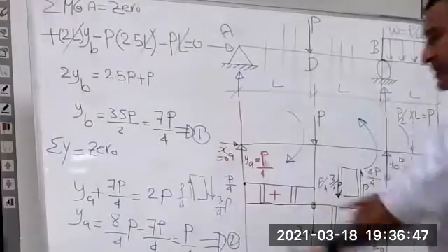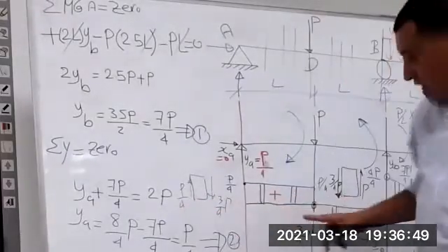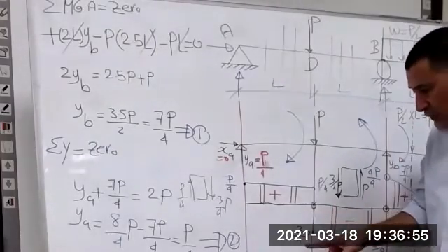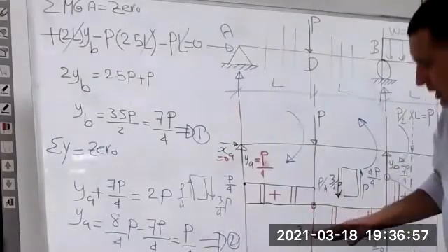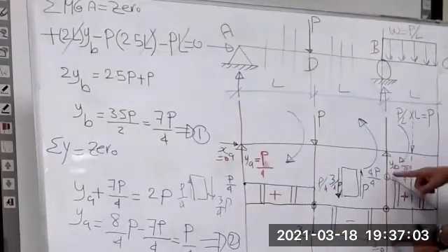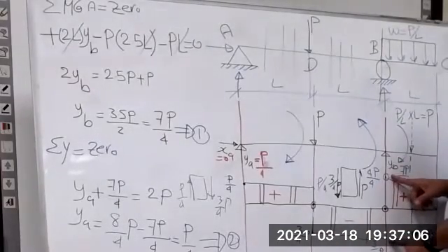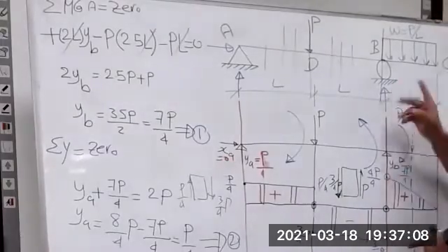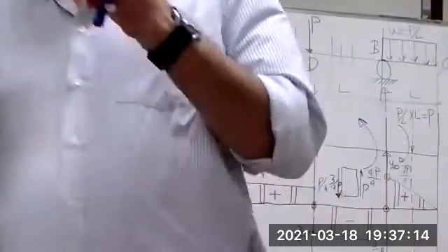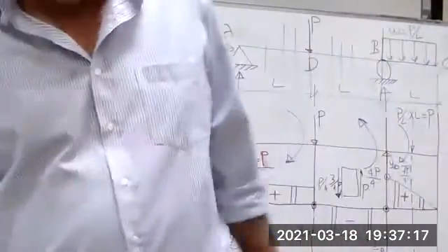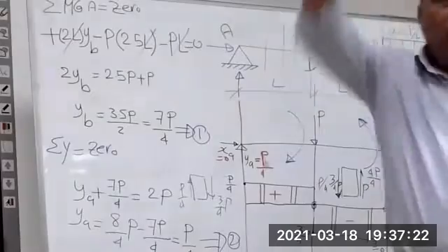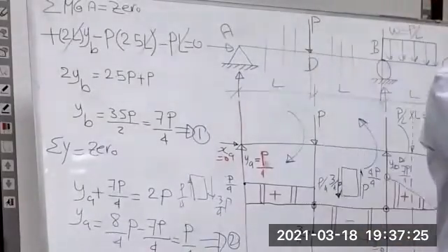You have right hand side, left hand side. See? You have the shear force here in this section, the maximum in this section. In this section it is 3 over 4 B. The section goes straight down, 3 over 4 B, until I reach the support. Because there is a support, the support tells me the reaction. The reaction is not shear force. Reaction is reaction. Shear force is different: force up and down. You need to cut the section.